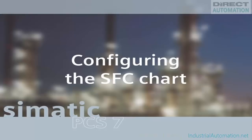In our example, there are two identical process areas or units in the plant. Automation of both of the units must be carried out in such a manner that one unit is fully engineered first and tested prior to beginning configuration of the second unit. The automation programs of the first unit are then copied and adapted to the second unit.